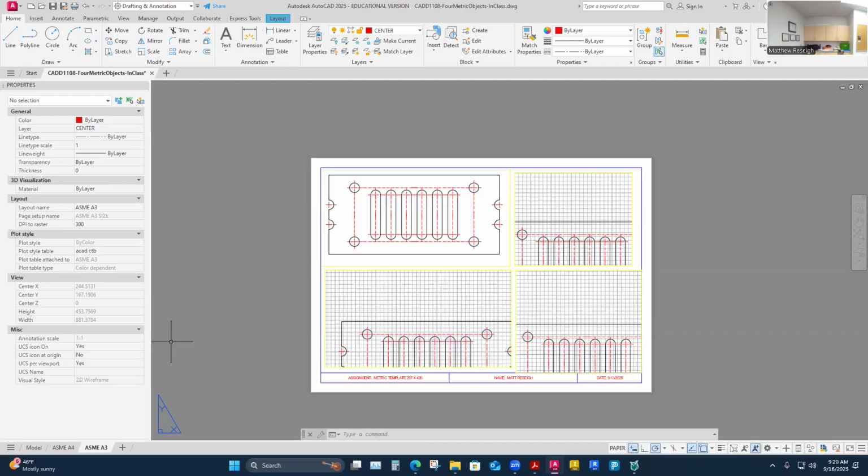Yeah. I did, but I did it on my drawing, not there. Okay. Yeah. Otherwise, you're gonna change the line type scale when it's at 1-to-1, and then you're gonna go to your half scale, and it's going to apply a scale on a scale. You can do that, yeah, or actually I just do it on the paper. So you've got that one at the 1-to-2 scale, right? Yeah, I think it's locked down, so now's a good time. This is where I did my line type changes.